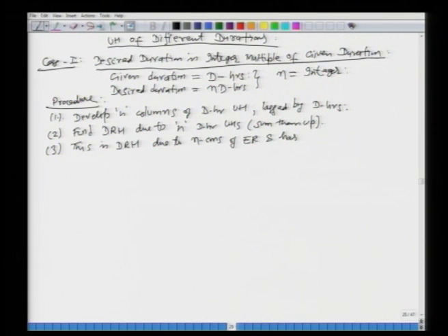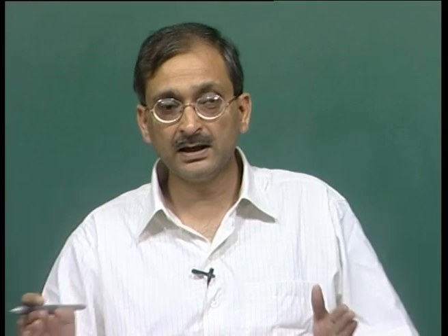And it has a time base of... I am going to use prime here to define the modified time base, which will be the time base of your original unit hydrograph plus n minus 1 times d. Okay. You can verify that. Now, we have a direct runoff hydrograph with us, which is produced by n centimeter of rainfall, and this n centimeter of rainfall occurs in how much duration?